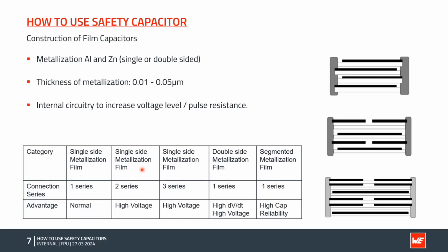For the safety products, of course, especially the Y capacitors, because they have to fail as a fail open. They have then a special construction to ensure that in a failure mode it's really open.